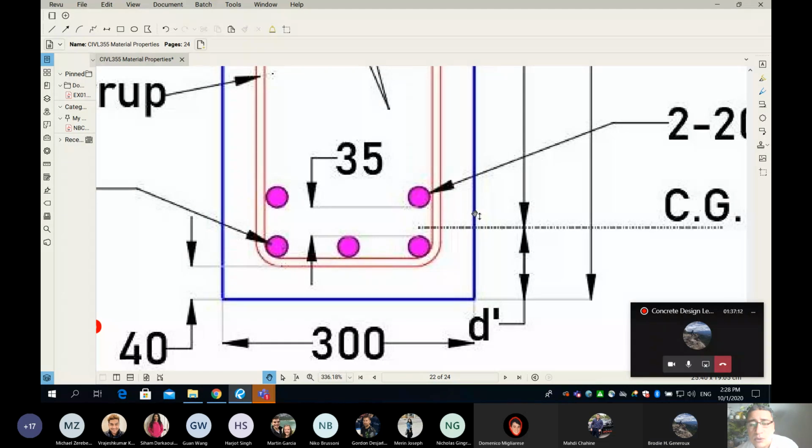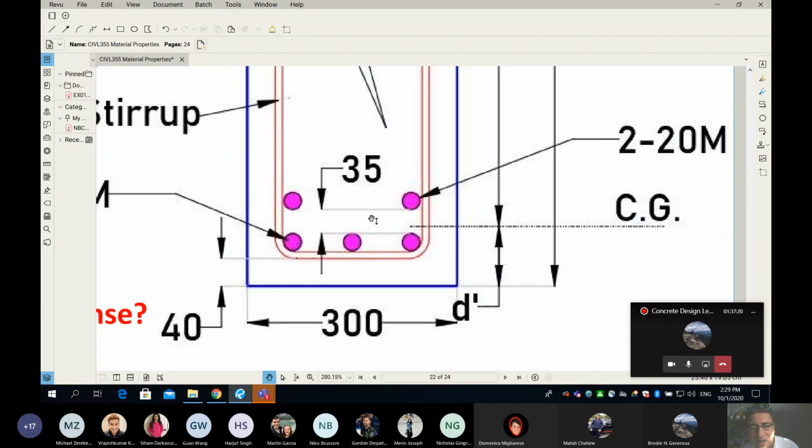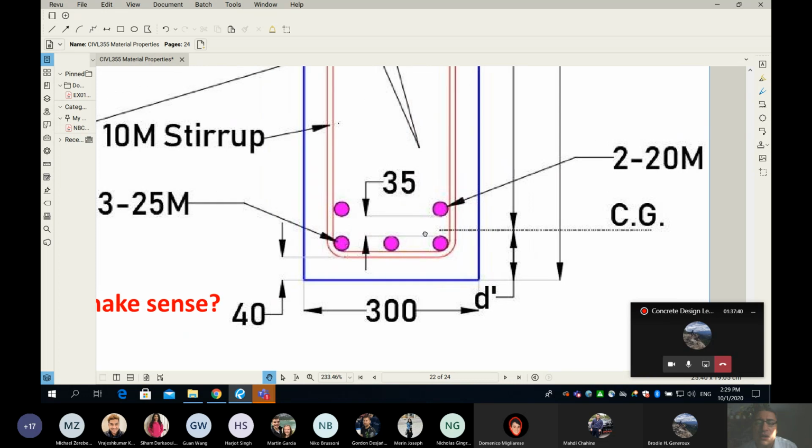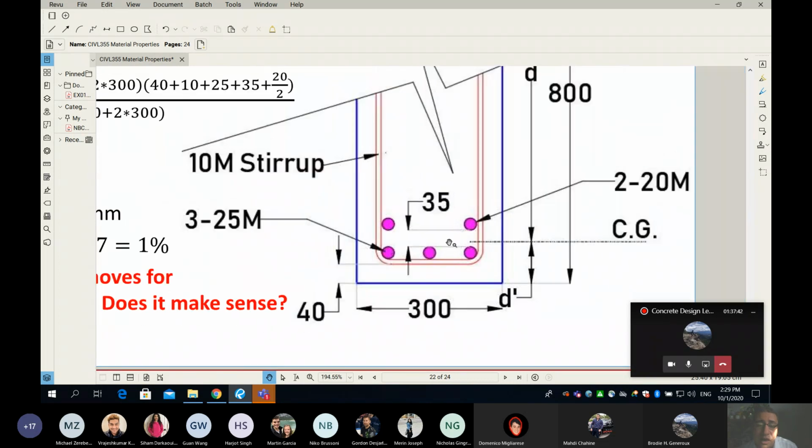So the answer is, my question was not that. My question, as I said, was: is it the same as the last question, where the centroid is in the middle? So the answer is no. I guess that's implicitly what it is. And the centroid will come really closer to the 3 because when we have more area, the more area will attract the centroid. So we have more area on the lower layer, and that's why the centroid will move closer to the lower layer.